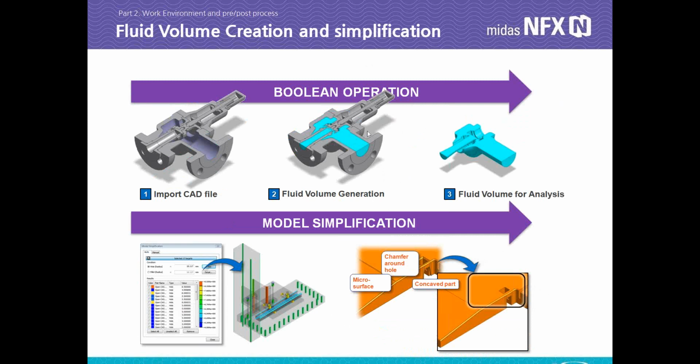As I was saying, it's easy to create a fluid volume using the fluid extraction tool. So you can create the fluid inside your part. And NFX has some tools also to simplify the CAD model. In case you have a lot of small holes or small fillets, it's easy to remove all that before going into the simulation. It's particularly useful when you're doing CFD, because CFD models need to be simplified to get a good mesh and accurate results.